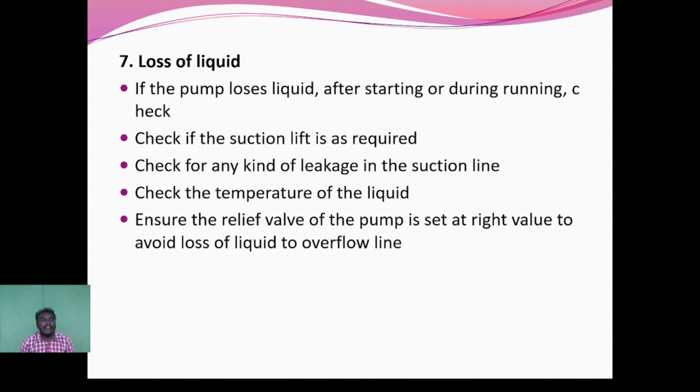Then the loss of liquid. If the pump loses liquid after starting or during running, we have to check first: whether the suction lift is as required; then check for any kind of leakage in the suction line; check the temperature of the liquid; and ensure the relief valve of the pump is set at the right value to avoid loss of liquid to the overflow line. These are the points that come under loss of liquid.